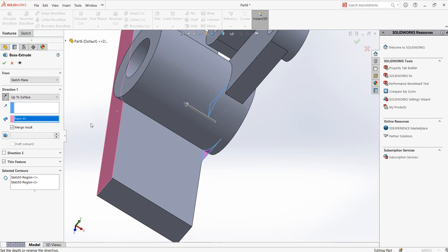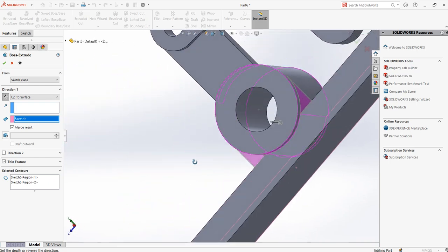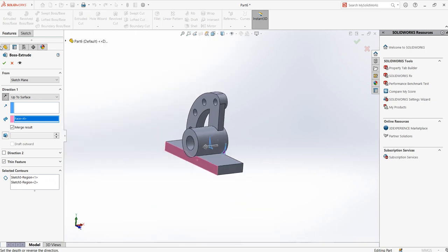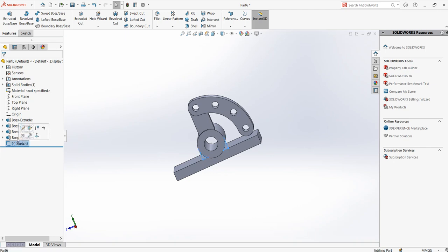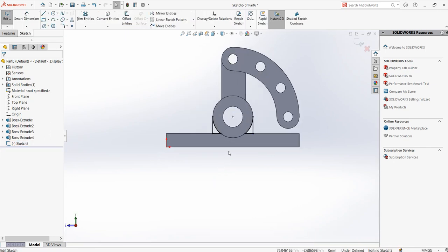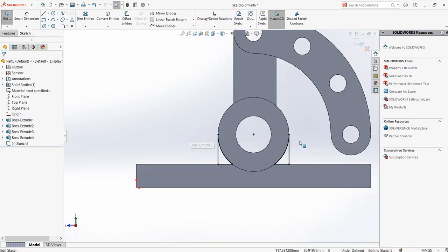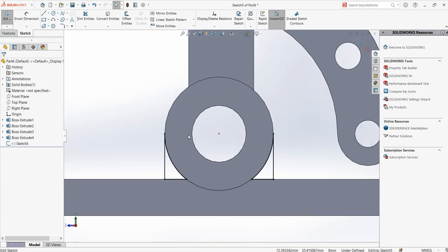Oh, that is the issue. Let me inspect the sketch again. Go to sketch, edit sketch. Sketch is okay here. Sketch is showing underdefined. So something is missing.